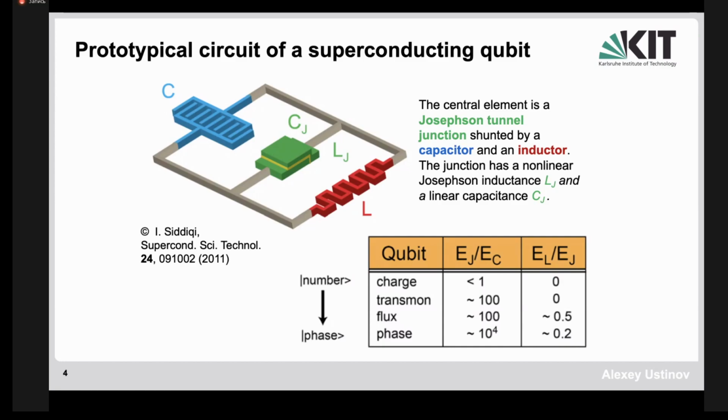An inductor is needed, for example, because if you make a very large inductor, then very small potential fluctuations which occur due to the charge noise, which you already heard about when we talked about quantum dots, are suppressed. Charge noise is really a problem for many small-size electronic devices. This charge noise will be reduced if you have some leak of the charge, which will compensate for the charge noise.